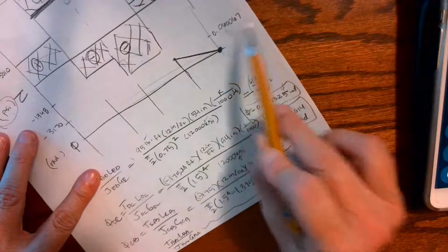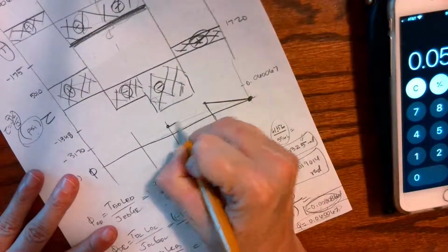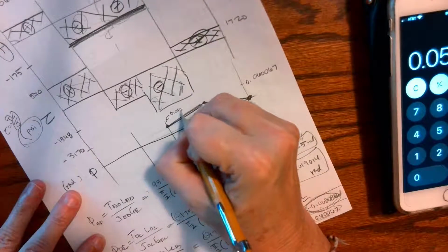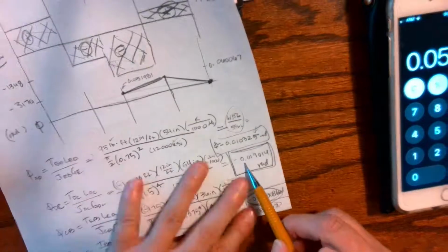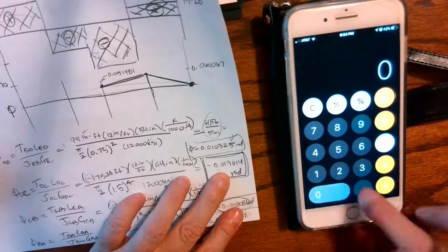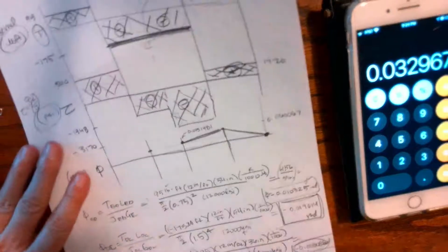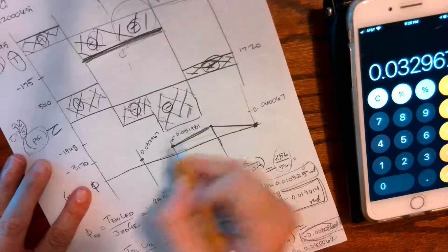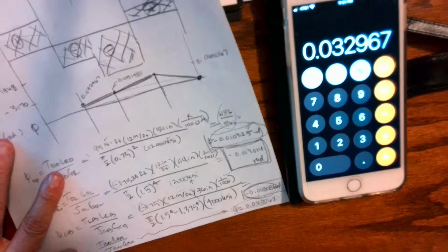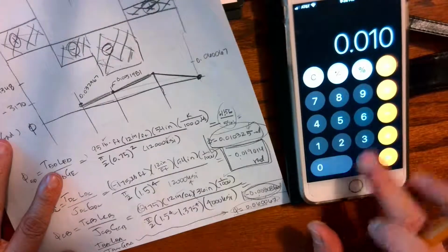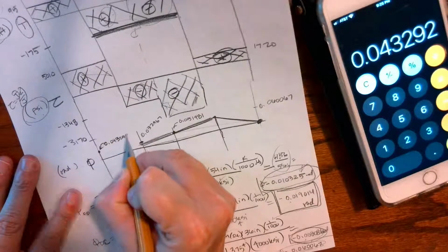So I'm going to take 0.060067 minus this, and I get 0.051981. So we're just a little bit left. Then, as I continue to move, I'm going to have another angle of twist. It's also negative, so it's minus 0.019014 equals, and I get this angle of twist of 0.032967. So I've come down even farther. And now I can add the angle of twist from segment 1, so plus 0.010325 equals. And I get an angle of twist of 0.043292. So it comes back up.